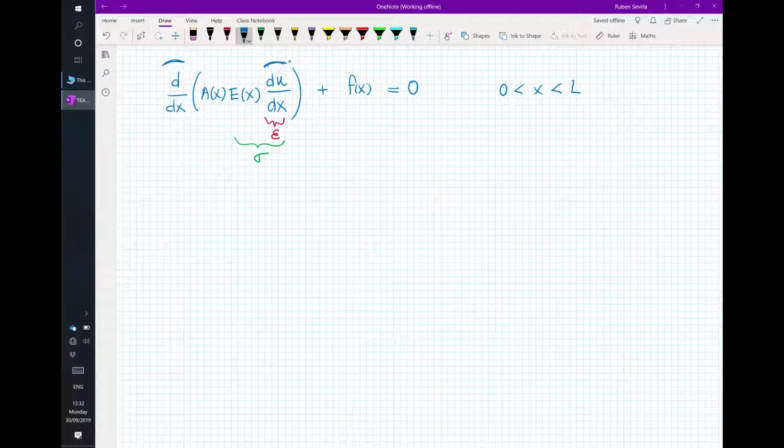That's the first question. I'll leave it there, because I think you need more than 5 seconds to answer it. Maybe more than 1 or 2 minutes. You actually need to sit down and write a bit. I'll answer it, but not today, so you have time to think. Anyway, partial differential equation plus boundary conditions, which for this example I'm saying one is Dirichlet, so imposed displacement, and the other one is Neumann, so imposed stress. Okay? Right.